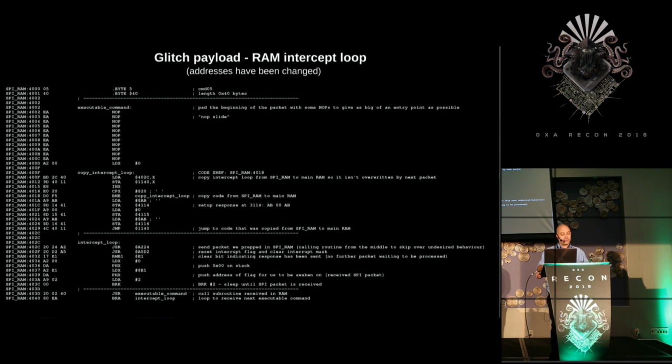At this point, there's several uncertainties, but so far I wasn't able to rule out this being possible. The ACP does run from an internal clock source, and the interrupt-driven task switching adds a little bit of further timing uncertainty. So I will send the code payload, delay, then glitch, and see the result. When it's unsuccessful, I change the delay and try again. I try to aim for the instruction I've identified as possibly corruptible to a jump, but there's so many unknowns that the process is like fishing. Throw a line out and hope.